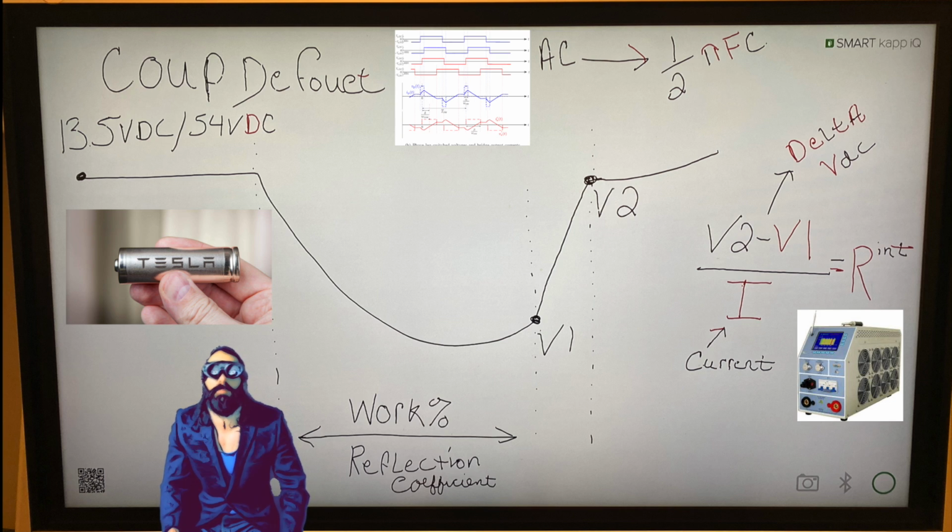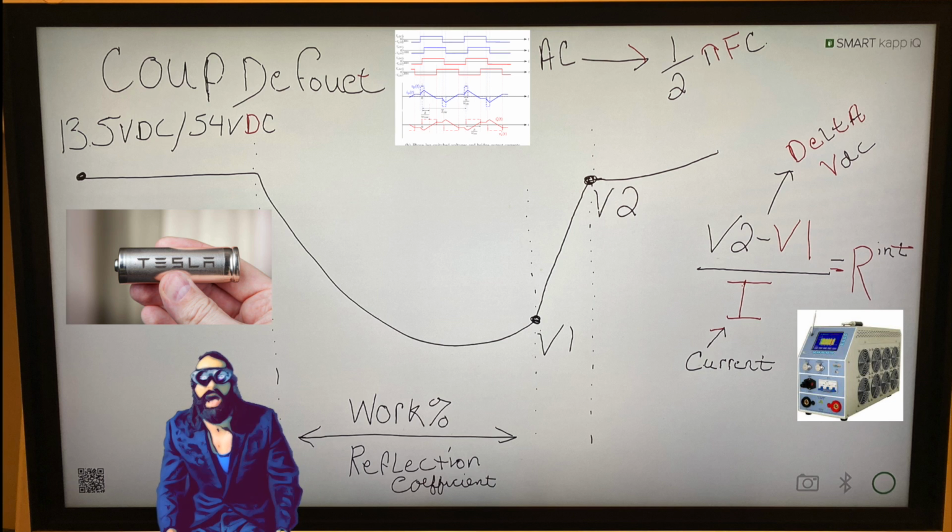And we talked about this in the previous 2 episodes. If you are expelling excess hydrogen, then the conductance, the conductivity of the battery decreases, because the glass matting, the insulation between the 6 2-volt cells of the battery decreases exponentially, right? It vents that hydrogen, it loses water. It's 95% recombinant anyway through that one-way pressure valve, 5 to 7 pounds per square inch. You keep losing hydrogen, you're going to lose water. You can't add water back into this. There's no reservoir for that. You can do it on vented lead acid batteries, so flooded batteries aren't as big of a deal, but on VRLA batteries, it is significant.